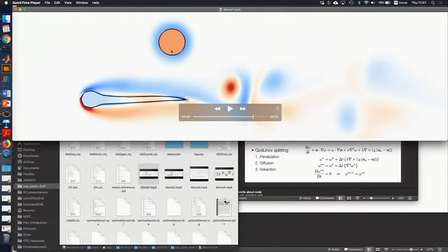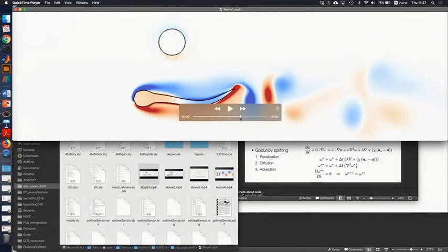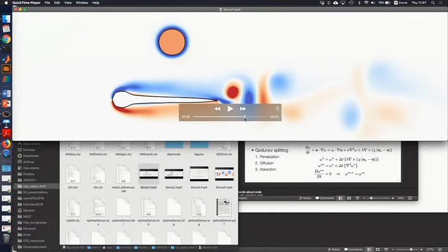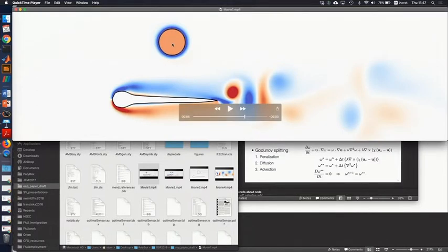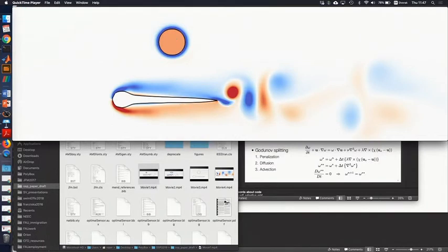And the color you see is vorticity. So all of the grid cells instantaneously change vorticity value. The cylinder rotates that way, so the fluid gets a negative vorticity. Everything makes sense. And what I impose here is that exact constant omega value. Each point inside the cylinder has some omega value, and once I know the radius, I can change it into U and V components. And that U and V is what actually gets imposed on the grid. Does this make sense? Yes.